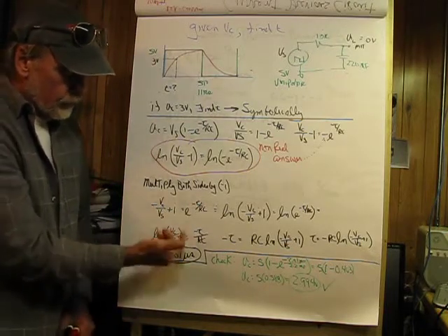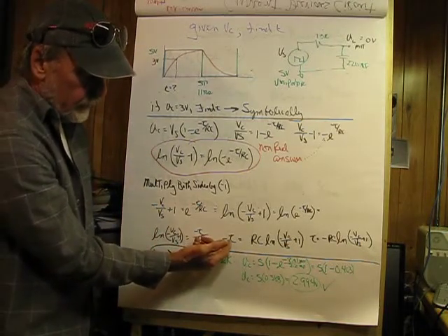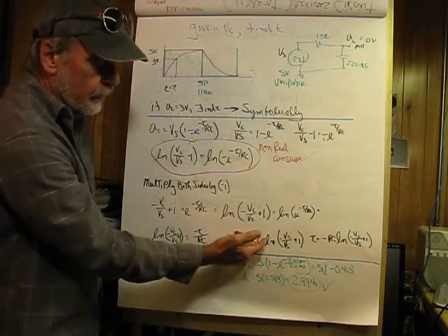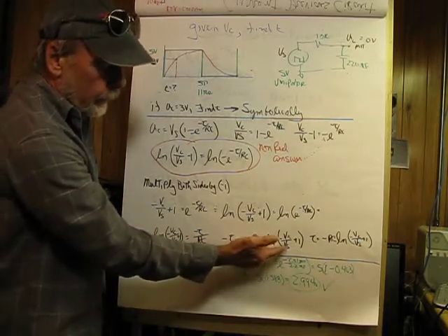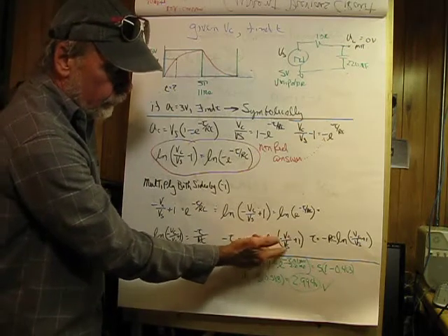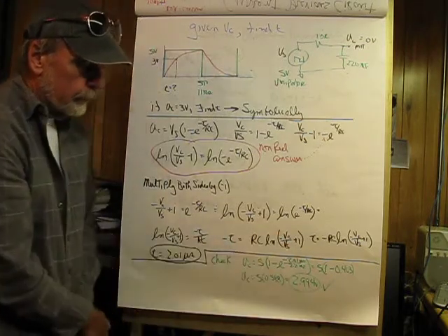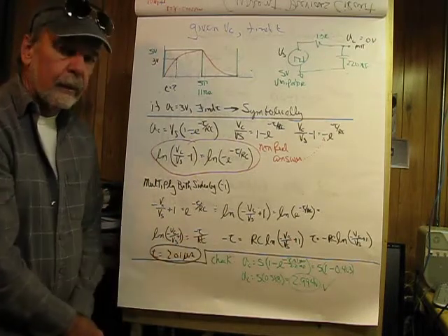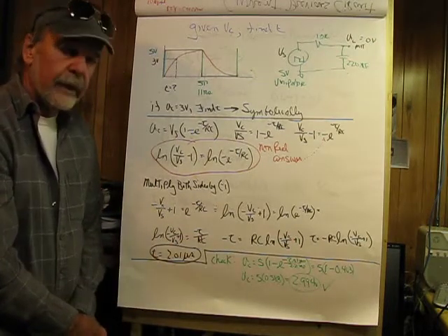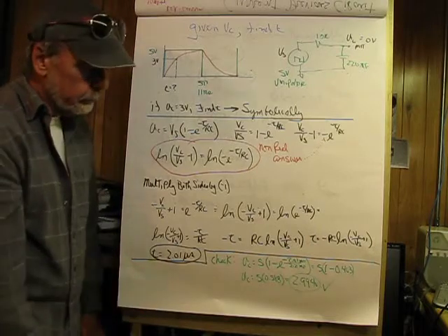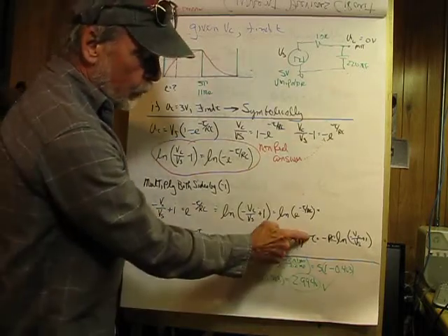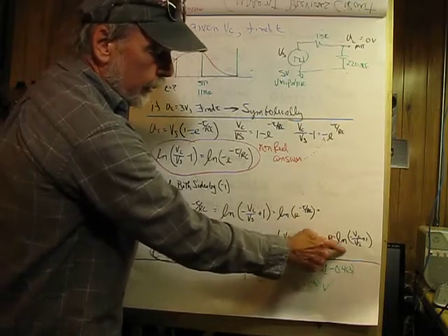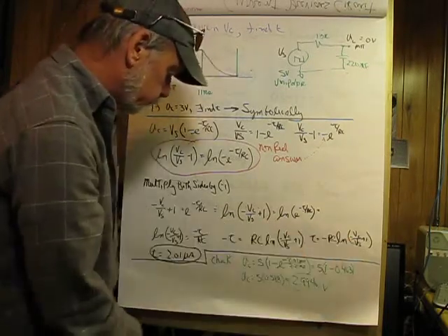So in switching sides here, we end up with negative t equals the product of the time constant RC times the natural log of negative VC over VS plus 1. So negative t isn't exactly what we want. So guess what? We have to multiply by negative 1 again. And in so doing, we get a positive t equals negative RC times the ln of this guy.